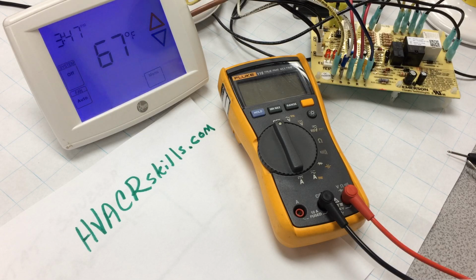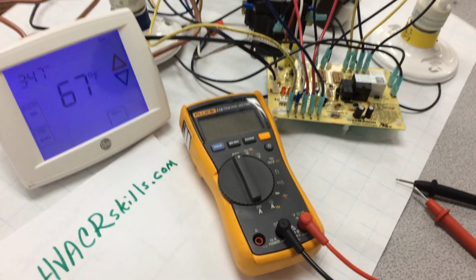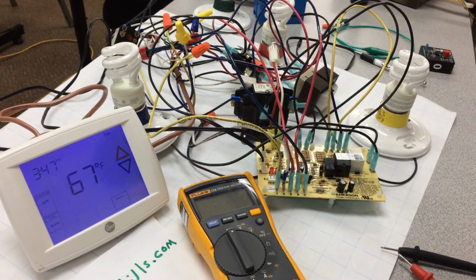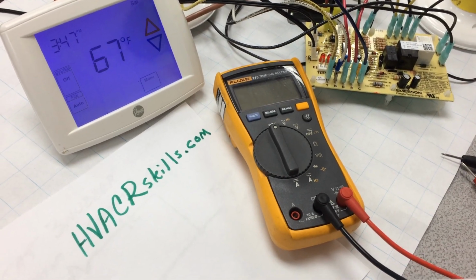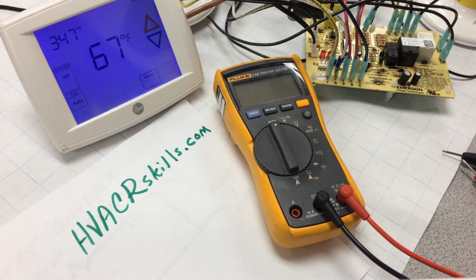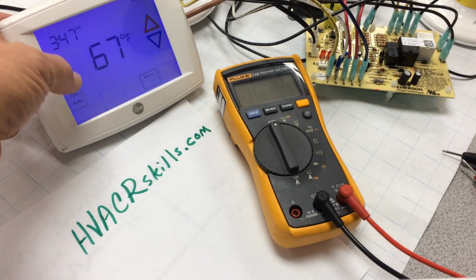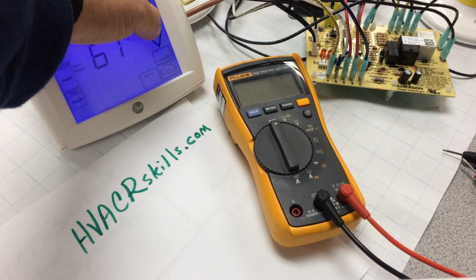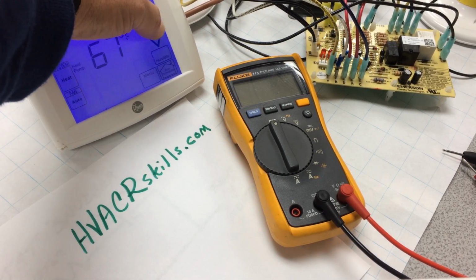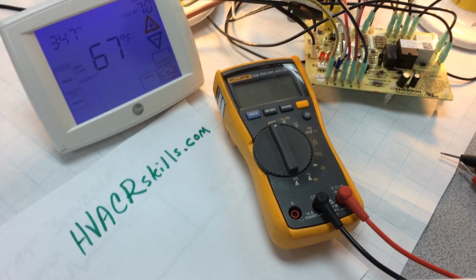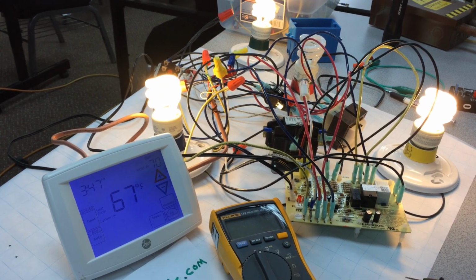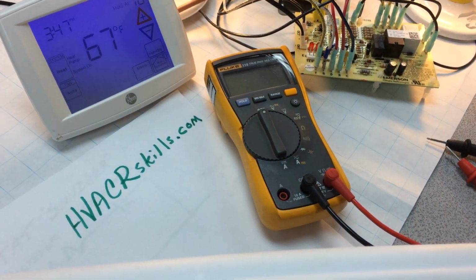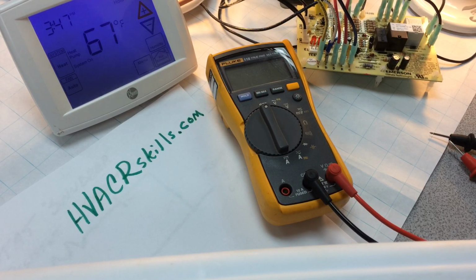First of all, we've got a functioning heat pump wired here on the table, and the only difference between a real heat pump and what we have on the tabletop is we've simply got light bulbs instead of the major motor loads. So I'm going to set this thermostat for heating operation and call for heat. We brought on our compressor and our outdoor fan bulb, and in the background is our indoor blower. So we're operating in first stage heat now, with this simulation.